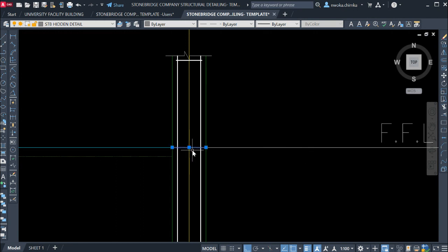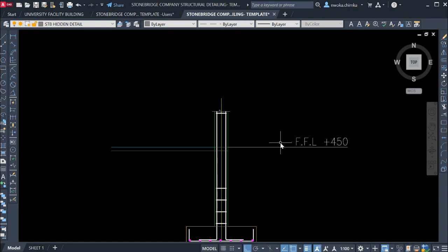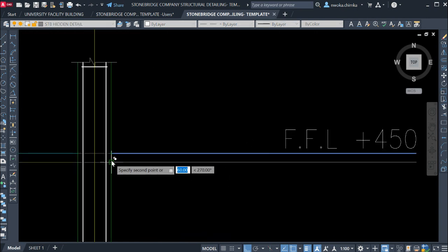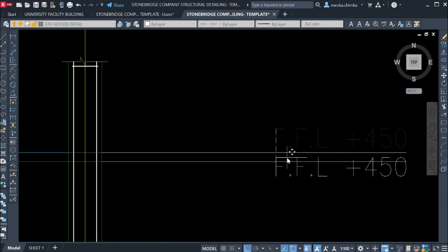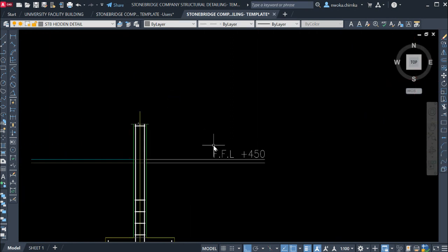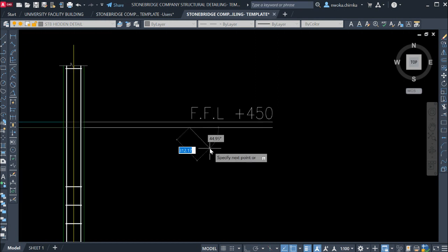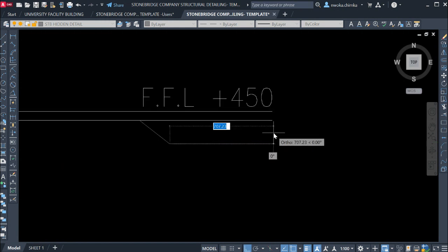Copy this again, and then bring this downward and keep it here. And then we go again, copy this line again, and bring it downward here. Now you can see that this is trying to clash between these two, so we cannot paste this here because it wants to clash. So what to do now is divert this line. Click on this plane to divert this line. We divert the line like this, and then make it horizontal again and keep it here.